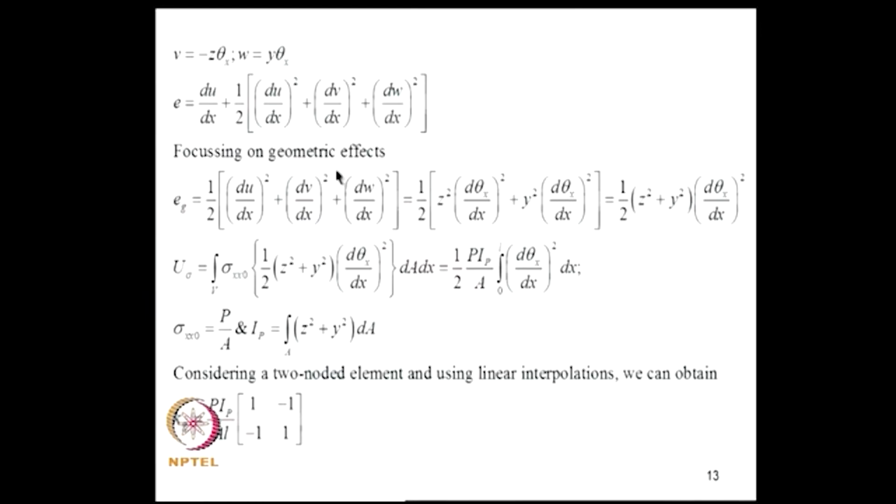Now, focusing on geometric effects, we have to include only the nonlinear terms. The linear terms contribute to equivalent nodal forces arising out of initial existing stresses, that is not what we are interested in. So, we compute the strain component, this G is geometric and this is what we are interested in, and using the assumed displacement field we get this to be given by this.